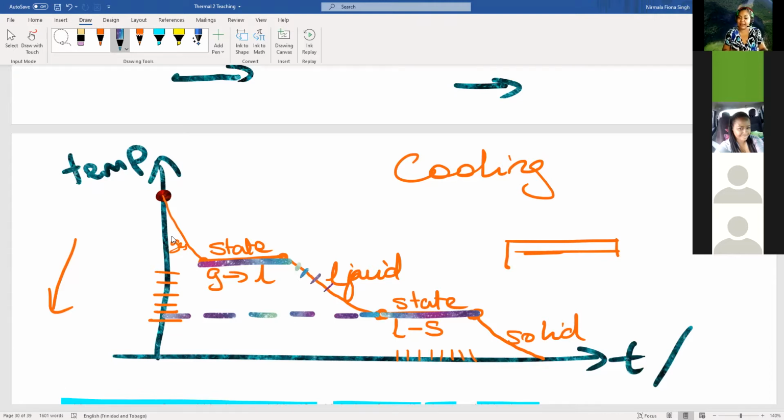So anytime you have a cooling curve, once it flattens out, you know that is a temperature where that sample, that material you have in front of you, or whatever the question is referring to, is freezing. So if anybody has started looking at questions and they give you a graph and say read off the freezing point, it's real simple. Just look to see where it flattens out.